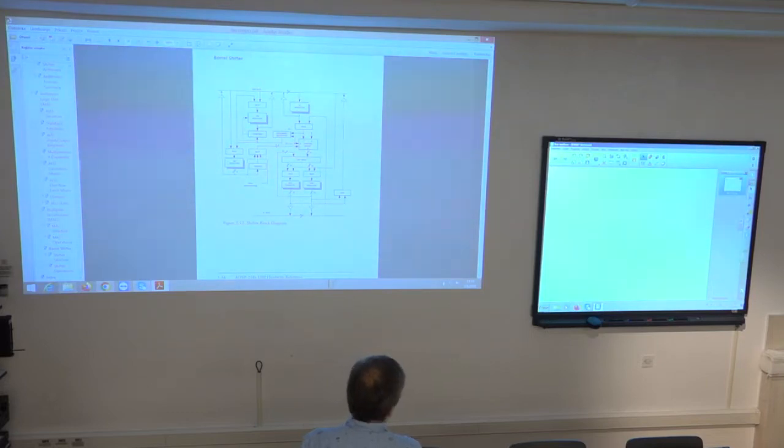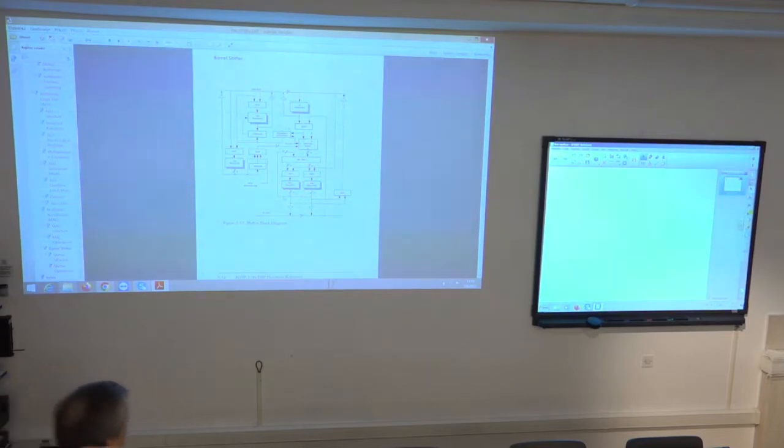It is the same architecture that I have described last time. We have this 16-bit input register and 32-bit output register that is composed of upper word, shift register 1, and lower word, shift register 0. Each of those is 16-bit. And we have this SE register which can hold the value how many positions I want to shift left or right.